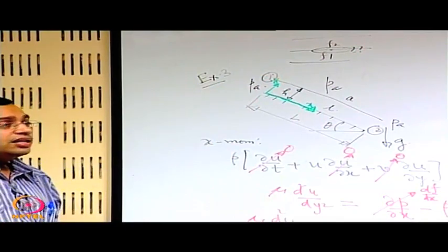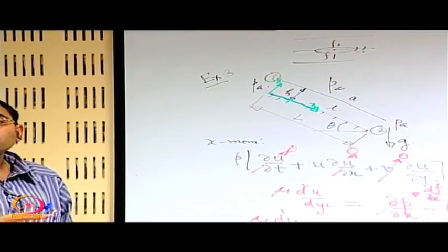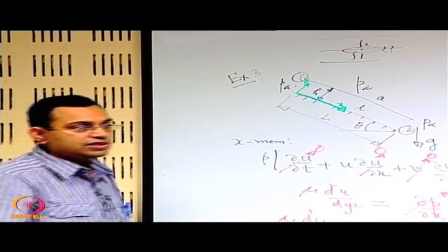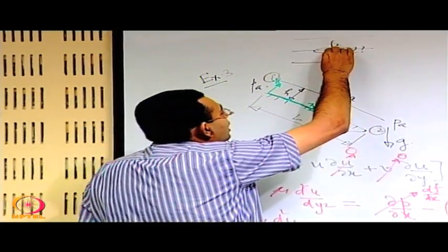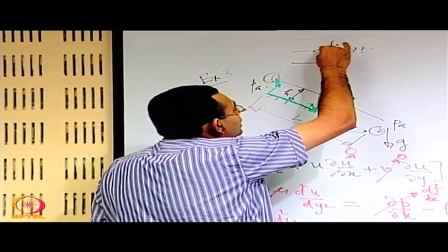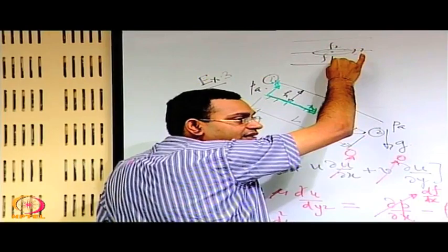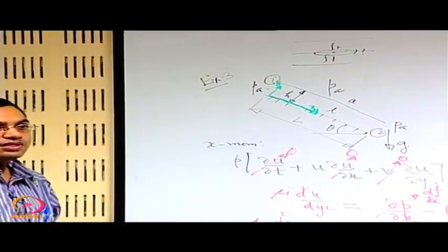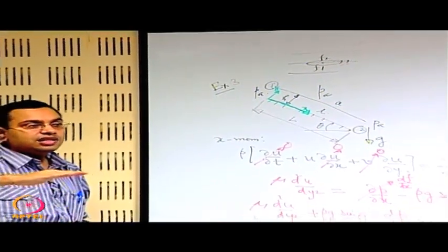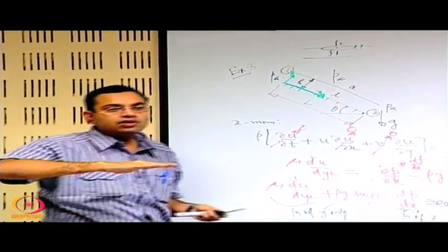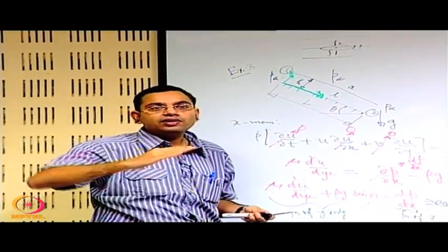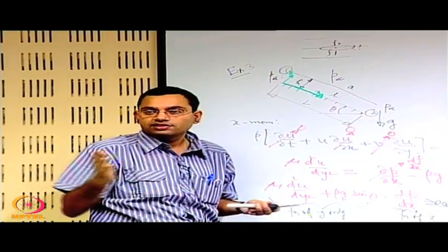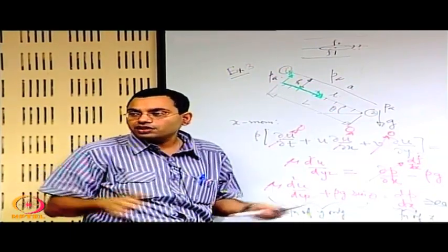The other thing is that there should be a continuity in shear stress, because whatever shear stress is at the interface on the fluid 1 side, the same shear stress should be there on the fluid 2 side. So it is a continuity in the shear stress, because at a particular interface there cannot be different momentum transport at the two sides. So the shear stress must be continuous.